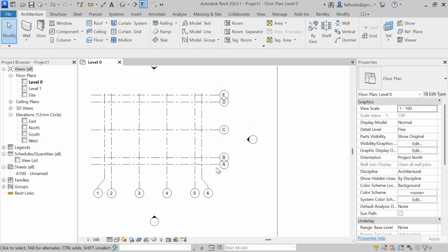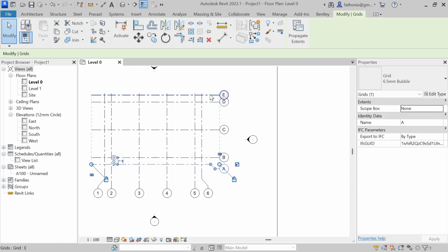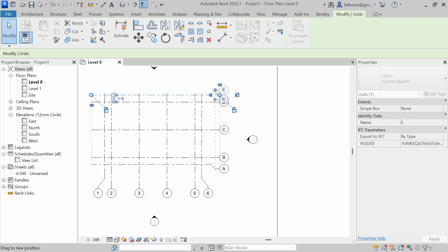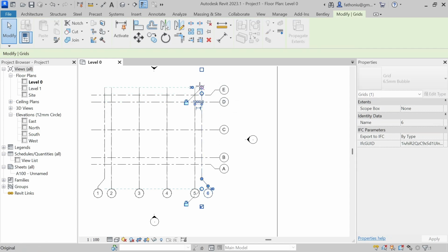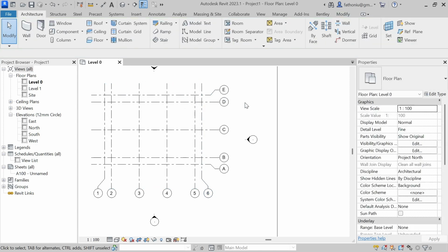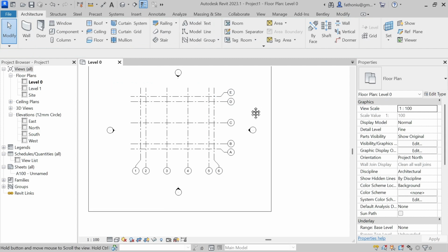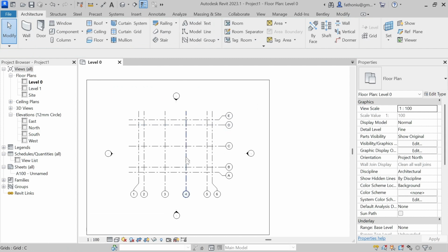Okay, then we do the same thing, create an elbow and drag a little bit. After that, we select one of the vertical grid lines, and then the symbol will appear, and then we select and drag. So make it just nice.